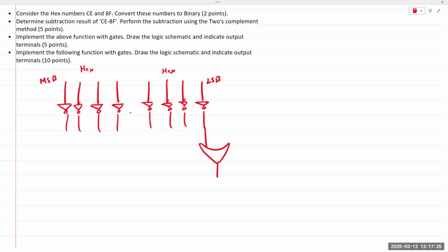If you want to add a 1, what do we do to this pin? Plus 5 volts or plus 3.3. Let's use plus 5 volts, which is something that each and every one of you did in the lab. When you created those circuits, there were many pins in those logic circuits that were connected to either plus 5 or ground.